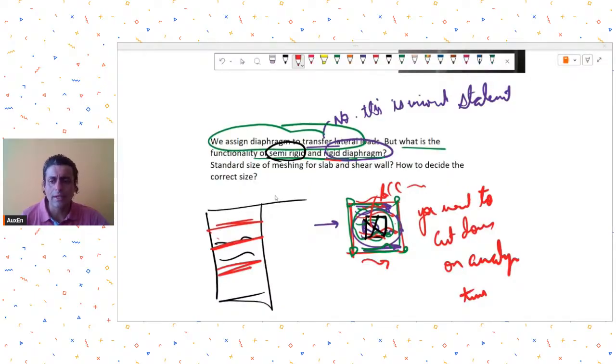So they have this problem of in-plane deformations possible also, and that's why they try to keep it as semi-rigid to see how the diaphragm is behaving. In the Indian context, where we have RCC slabs, most of the times it will have negligible in-plane deformations, and it will behave as a rigid diaphragm.